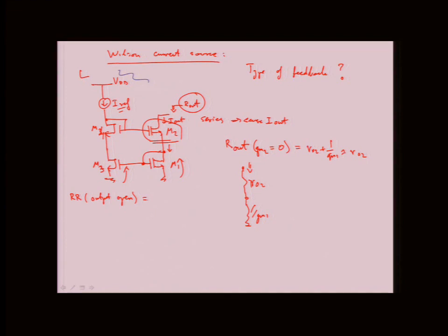Current is 0. So is there any feedback? Right? There's nothing to kind of pump into this M1 resistor. So therefore, you basically just open the feedback. Because remember, the output feedback is series. So there has to be a circuit that goes around, or the current goes around. And here we just opened that circuit. Right? So this RR of output open is 0.